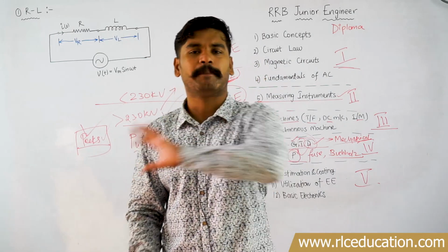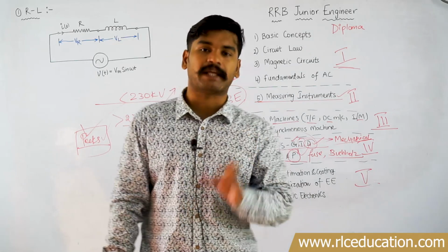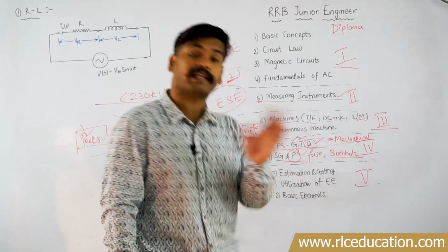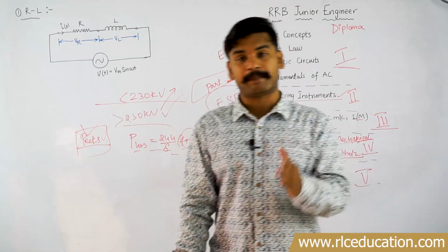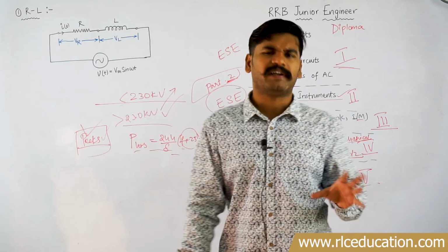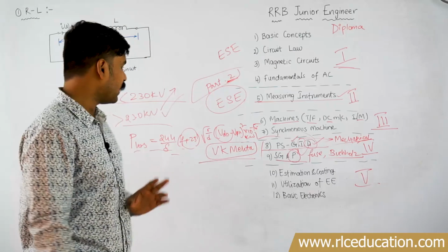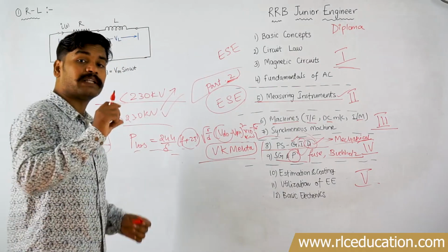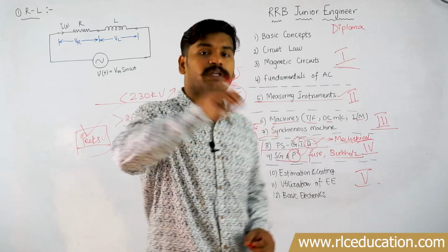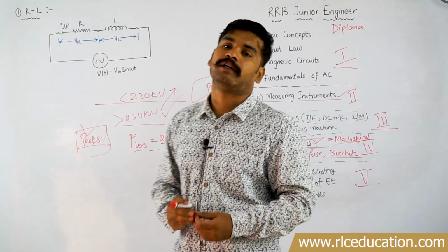At different points of a power system, you require different types of insulators. What are the different types of configuration of insulators? What are the other names? Like strain type insulators, shackle insulators, Hewlett type insulators, cap and pin type insulators, string insulators, whatnot. There are a number of types of insulators, and there are some design aspects about those insulators: flashover voltage, dry flashover voltage, wet flashover voltage, puncture, different definitions associated with insulators.